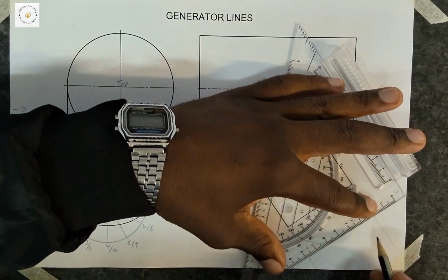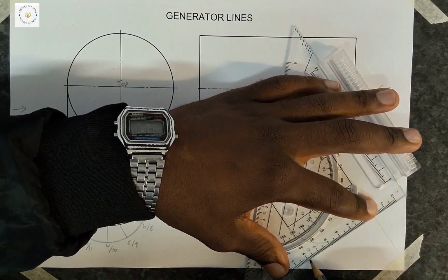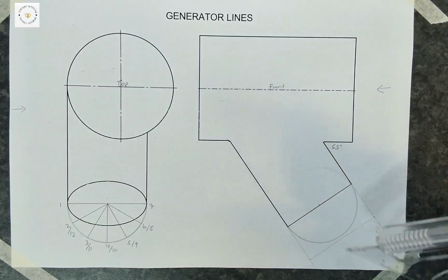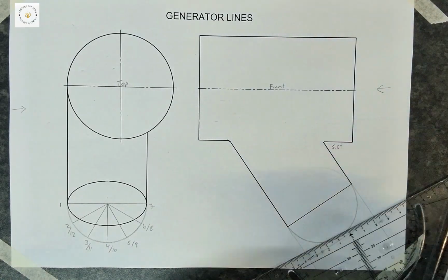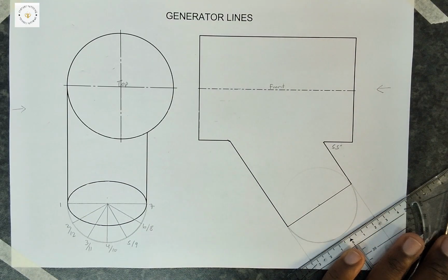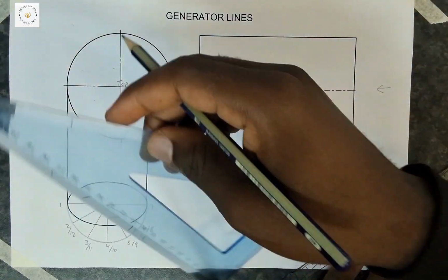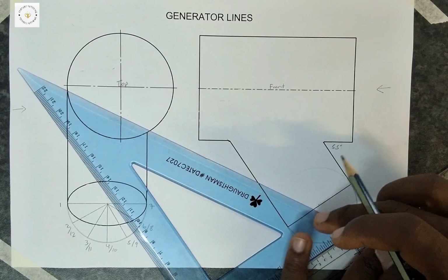Now what you see is that I am actually creating a parallel line from that. Why am I doing that? It's because now if I have a parallel line like that, I can just put my ruler, this ruler here, on that parallel line. Now it's acting as my t-square, right? After I put it there, make sure that it doesn't move, and then I can divide my circle or semicircle the way I divided that one.